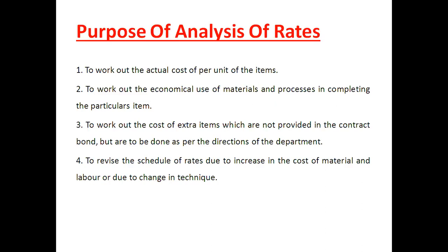30% fly ash we can replace along with the cement, depending on the class or category of the fly ash. So if you are going to see the cost of fly ash, that is again on the lower side as compared with the cement. So making, suppose, the cost of construction of 1 meter cube. Do you know the cost of 1 meter cube concrete, or one brass of concrete?